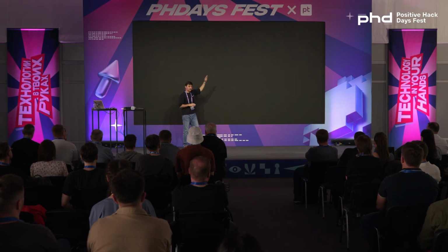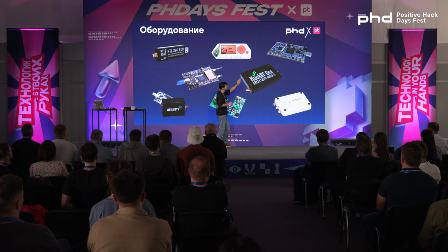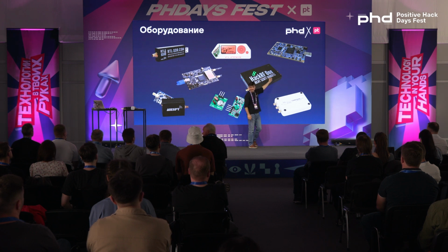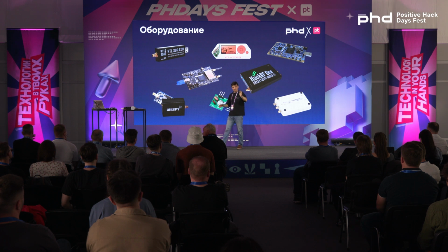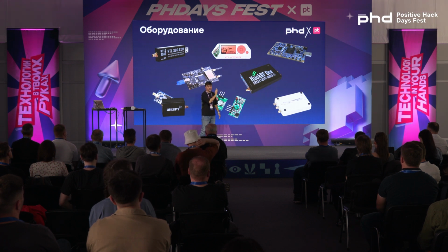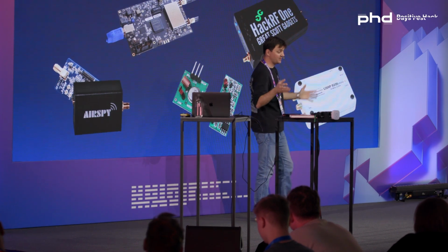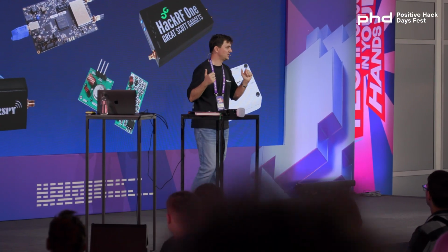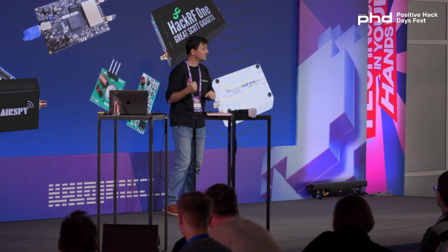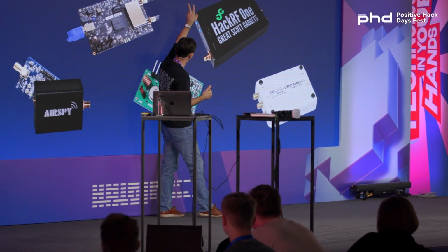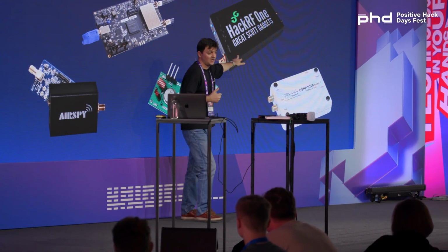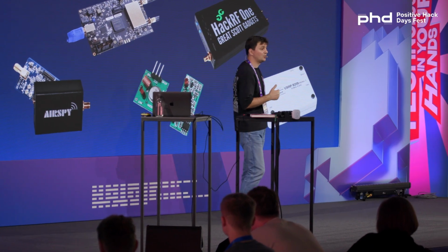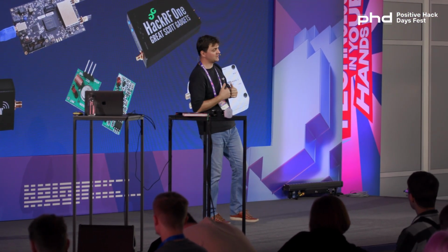LimeSDR, a very expensive thing, a professional thing. The main drawback is price. It's too expensive, and sometimes it's very difficult even to buy it at any price. The main feature, you can transmit and receive signals. It can work simultaneously. For example, Flipper Zero and HackRF are half duplex equipment.